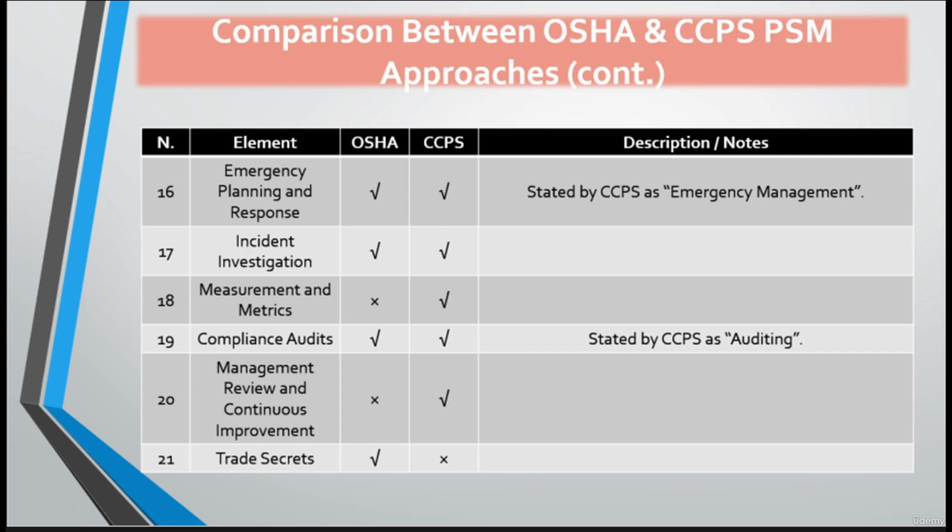So, in the end, I can tell you that both approaches are quite similar to each other. However, CCPS took the risk-based analysis of all individual elements of OSHA. So I guess you should start with the OSHA PSM standard, and when you feel that you have fulfilled the requirements and you have achieved good results through the compliance auditing programs, I believe you should continuously improve the system by going to the CCPS approach.